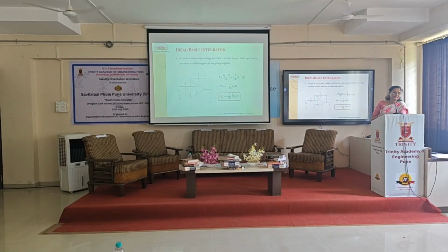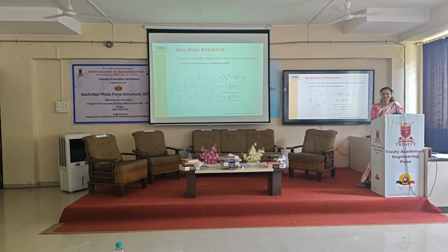And after that, the next application again is the integrator. Students already handle capacitors and resistors so many times. Now here they are going to implement the integrator using RC components along with the operational amplifier, which works as an integrator. In this case, again by taking the help of the virtual ground concept, the derivation is coming for the output equation.